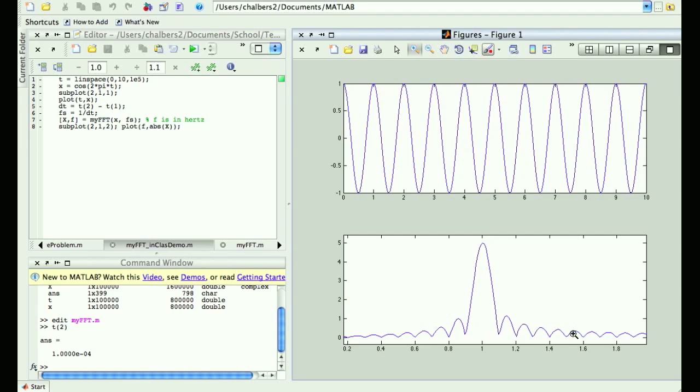We're going to put all these pieces together. It's like a big jigsaw puzzle, and I've got to figure out how to get all these pieces onto the board, and then eventually it'll all connect. But your take-home message for today is that, first of all, we talked about the square pulses in a bit more detail, and then we started to mess around with how you use the myFFT function to make these plots. And again, it's very easy to use. You just have to know the sampling frequency of your time signal, which isn't hard to calculate. When we come back on Monday, instead of taking the Fourier transform of the cosine, we'll take the Fourier transform of a rectangular pulse, and we'll make sure that what MATLAB plots for us is exactly the same thing that we got by hand.